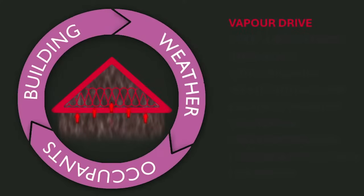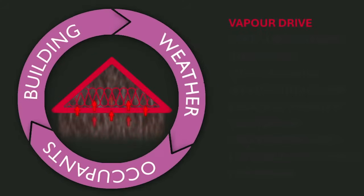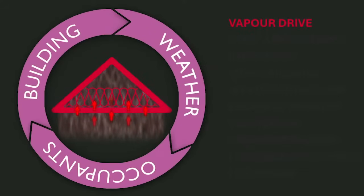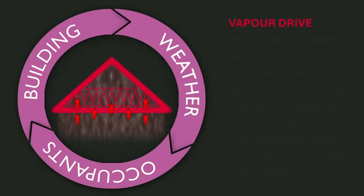Off-site construction, such as timber frame or SIP buildings, will also tend to have lower moisture loads, as there are fewer wet trades to dry out, and the building is usually wind and watertight earlier in the construction process. The construction moisture can lead to significantly higher condensation risks in the short term after completion. The vapour drive present determines the overall condensation risk that will be present, and as such is the start point of the hygrothermal assessment of the roof's performance. Should subsequent repair or upgrade work, such as adding MVHR or a change of use for the building, have the potential to affect the indoor environment, the performance of the roof systems should be reassessed to account for this.